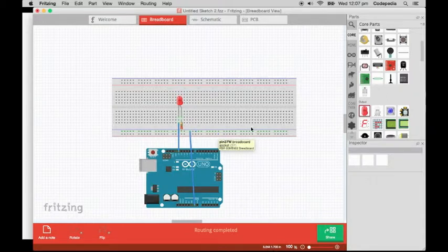This row on this breadboard is really good, as I stated in the previous video, for attaching a whole lot of negative ends or even positive ends of components into just one row, so you have one wire as opposed to heaps to different pins on your board, whereas we now just have one wire running to a ground pin. It doesn't actually matter which ground pin, but today we're going to be using one of the ones in the power section.